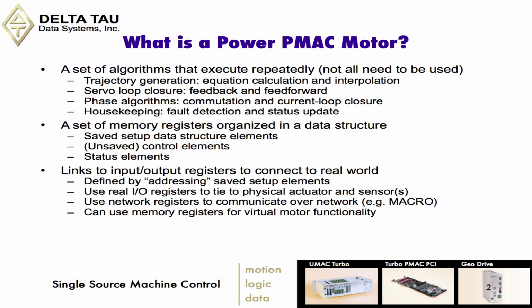There's linkages to input and output registers to connect the motor to the real world, defined by addressing saved setup elements. Remember, we talked about the elements that would have the lowercase p in their element name, indicating that they're a pointer to something. So that's how we take the software creature called a motor and connect it up to all of the real hardware. All of the stuff that we just talked about, these ASIC registers, are all done by these pointers.